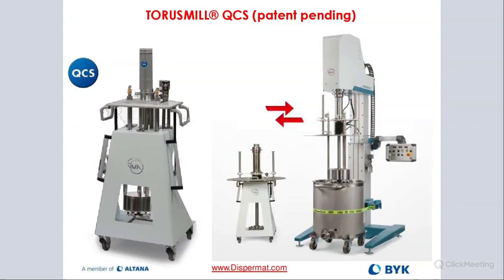So I can tell you that we have done quick changes in under 5 minutes. So it's very easy to do. You don't have to be strong. You can just basically remove the container, put the trolley underneath, lower it, then basically remove a clamping ring, turn it slightly, and it comes right out. And then put the other trolley underneath, and then you basically lock it in place and then lift it up. So a very easy and quick way of changing from a dissolver to a basket mill.